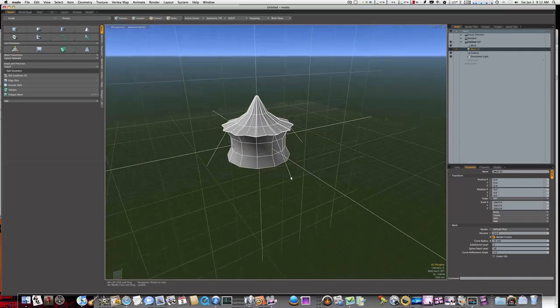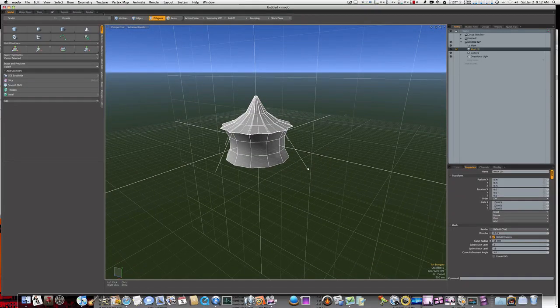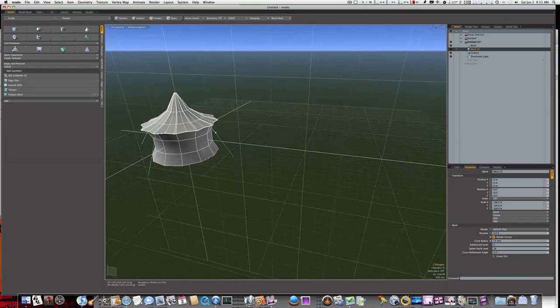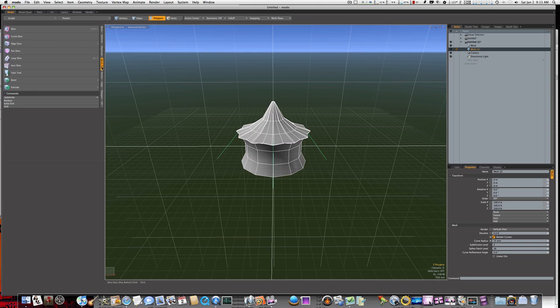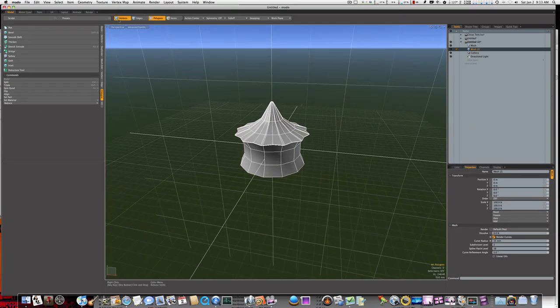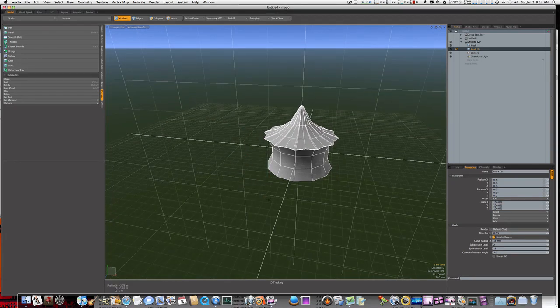Okay? So, instead of copy, let me give you another example here. Let's go to our polygon mode. I'm going to select these curves that we just laid down, and I'm going to remove them and get rid of them. So now you can see we only have that one. But I need to go in here and get rid of those little verts that were left that I didn't get rid of by mistake. You can see there's a little vert left where the curve was.